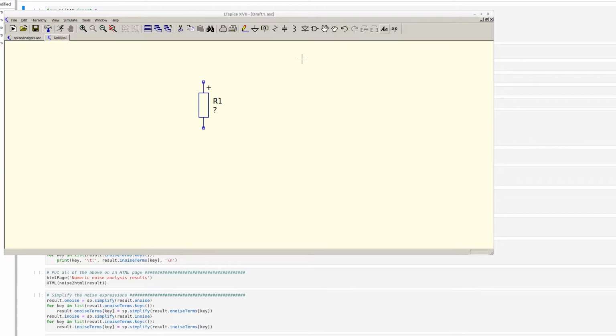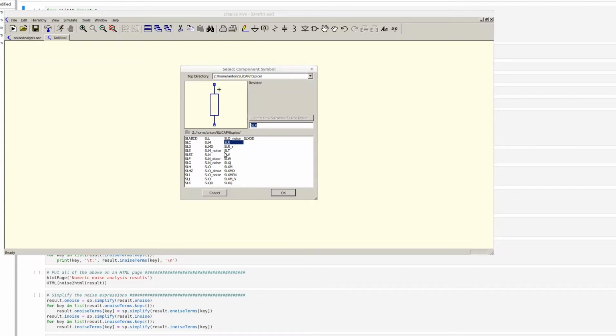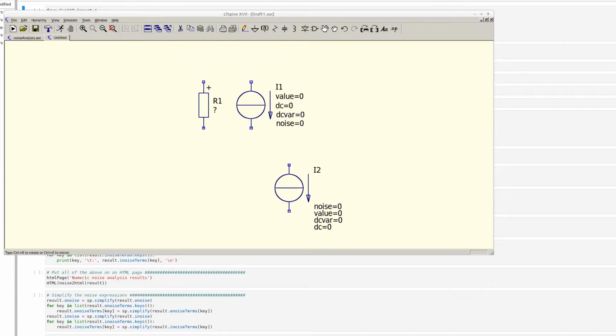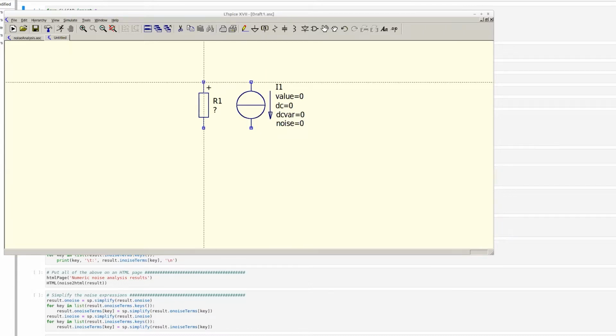The best thing is then to place a current source in parallel with it. And why not a voltage source in series? That is because of modified nodal analysis. Modified nodal analysis is based on nodal analysis, and every voltage source you add will give you an extra variable in the matrix and makes your matrix larger. And inversion of matrices or determination of symbolic matrices, the cofactors from it, is a tedious job.